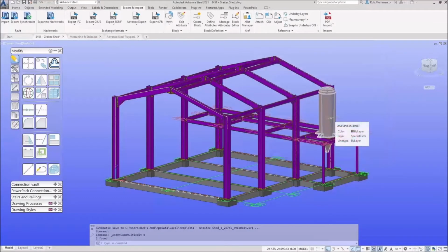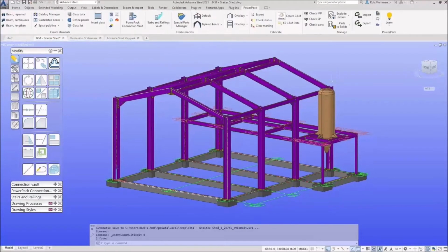Now, the current workflows with the SMLX file, special parts, they are included in the SMLX file. If I brought this SMLX file back into Advanced Steel, it would create the special part, but there's no functionality in Revit to create a generic family from an Advanced Steel special part. So we will have to do that one separately. We need to copy it into a separate file, explode the Advanced Steel intelligence and copy it from 000 to 000. And then we can link it in.